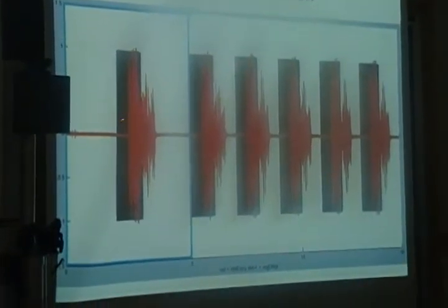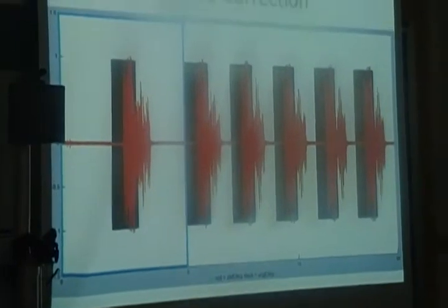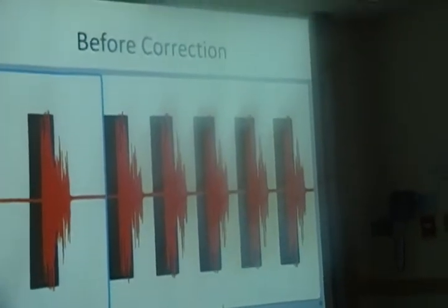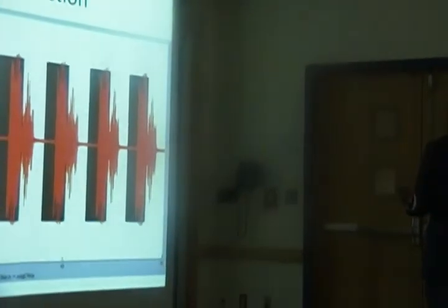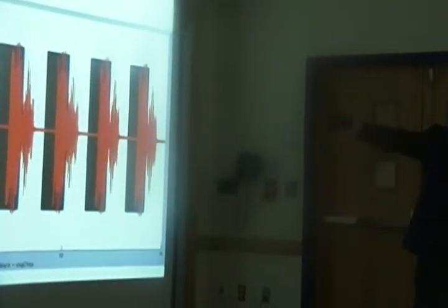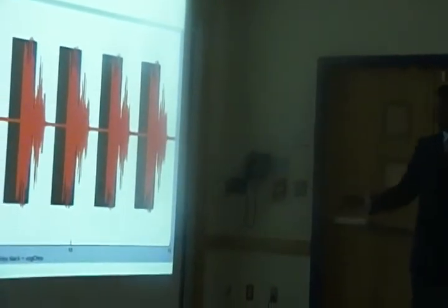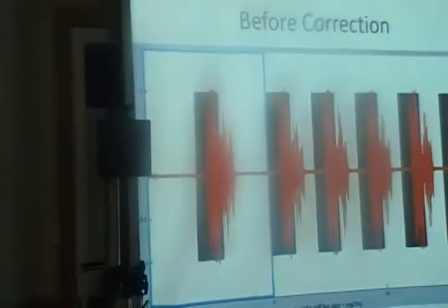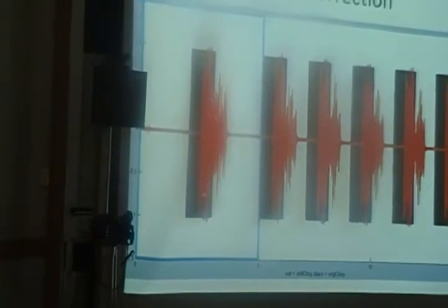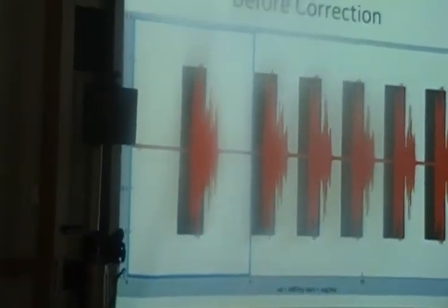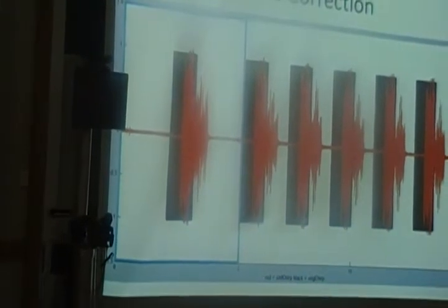And see, what I did here was, part of this is random delays, part of it is constant delays, and part of it is I waited 1 second before I played and started recording. So I added this delay here. For the initialization point, you have to know the first point that you're measuring. For this point, in this blue box here, we assumed that it was a 0 for this test. All the other chirp sequence is off by this latency. So we correct for it based upon this chirp here, and then we move all the other ones. So all the other chirps were actually at 0, and now we measure it correctly.